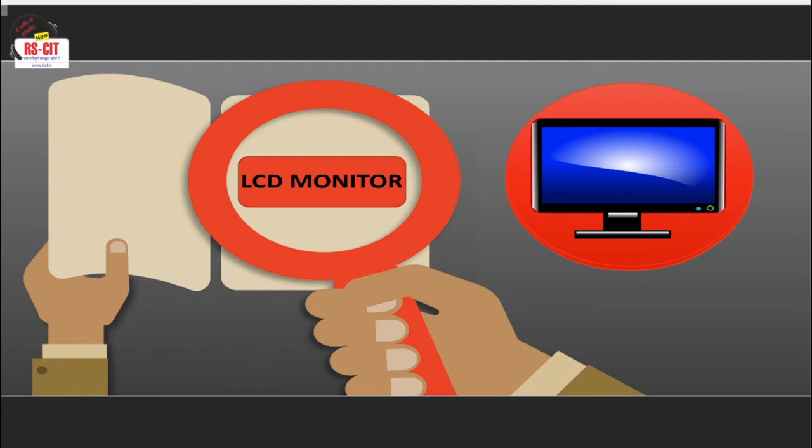The latest LCD screens use transparent thin film transistors, that is TFT, controlling each pixel, so the picture quality and viewing angle are much improved. LED monitors use light-emitting diodes that act as a performance booster in the monitors. Basically, LED monitors are the LCD monitors with an LED backlight to power up the LCD panel.